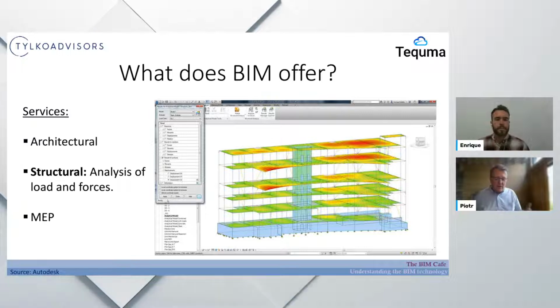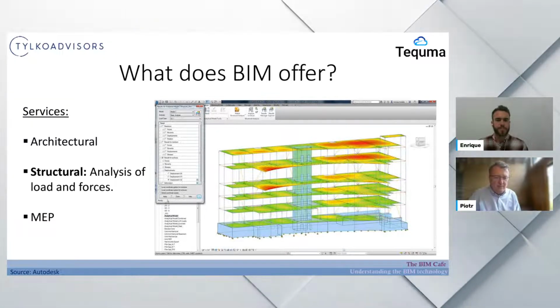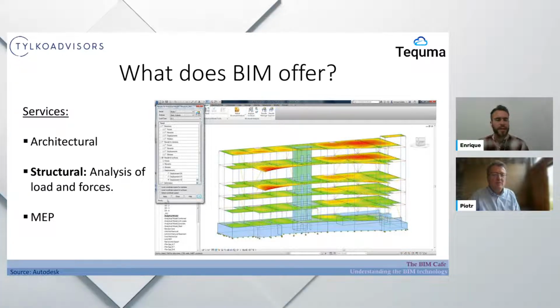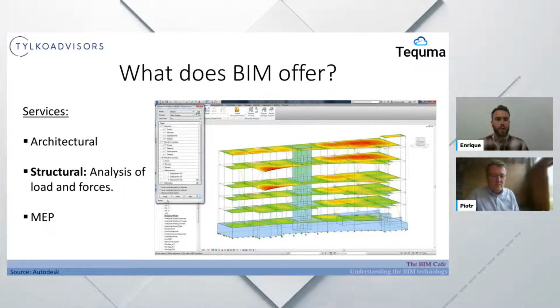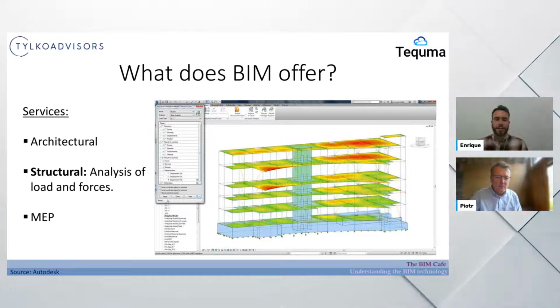If the manufacturer I chose before was not keeping the right parameters for my whole building. Yeah, okay. In this example, you can see there are some red parts on the left side. These are going embedded, and maybe they won't stand the structure. In this case, okay, I can try and change the materials of the ceiling or of the floor to a lighter concrete from a different manufacturer or the same one, and instantly this coordinates and updates. So you see the result. Okay, will this lighter one work better here or not?